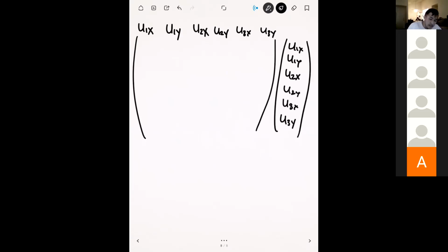Okay. And let's say in this case, we have node 1 to be completely fixed. And so if node 1 is completely fixed, then normally we just replace this with zeros like this and a 1, right? And then we just are along our merry way, right? But what the book tells you to do is that if you know node 1 is fixed, then there's actually no reason to keep it in the stiffness matrix.